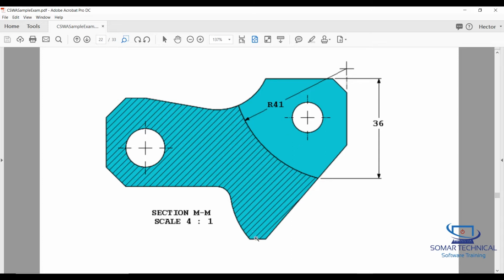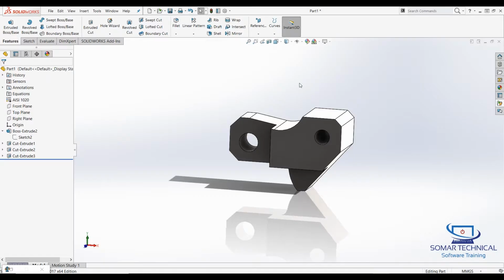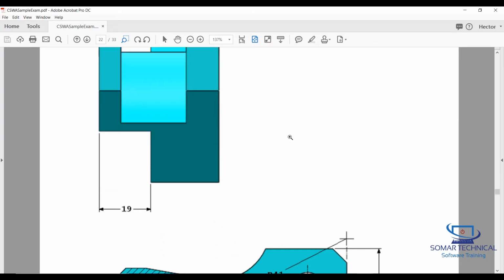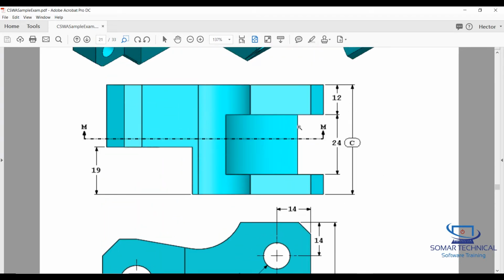I'll show you guys how to do that one a little quicker, I think, than what some of you might be visualizing. So let's go ahead and do it this way. One thing to note is that this cutout is not at the very edge. It's 10 millimeters off, and then you have a total cut of 24 millimeters. However, I am going to sketch it on this face.